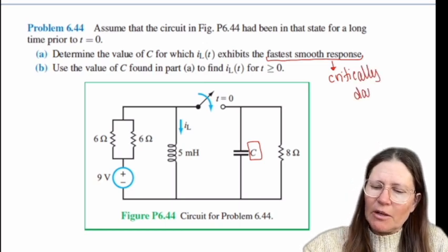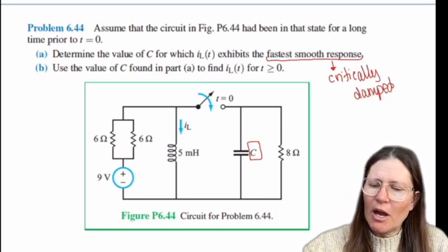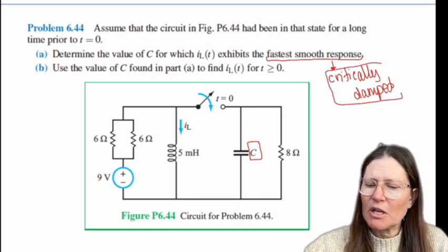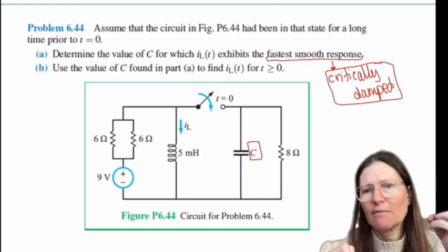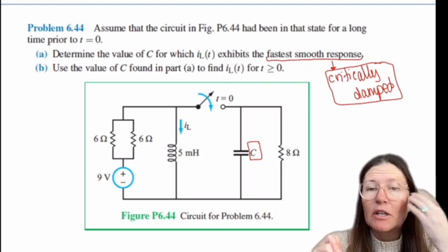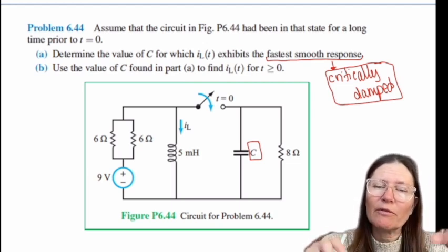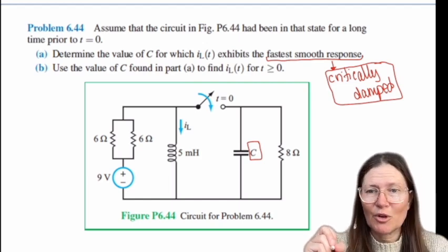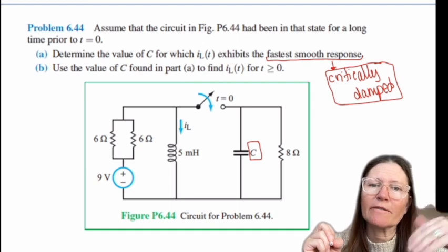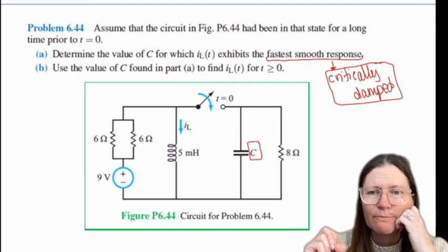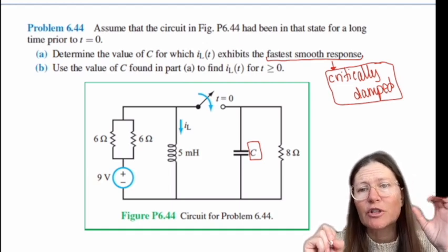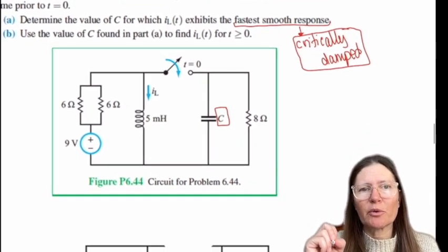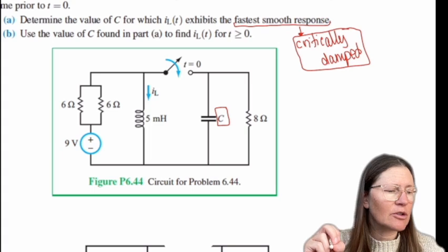So critically damped, we want to have our roots to be two of the same value. So the characteristic equation, you can solve this first by doing, you can go back and watch the other video where I find it with the transfer function. From that transfer function, you can then take those variables. The other option is just to use the table that already has solved this.